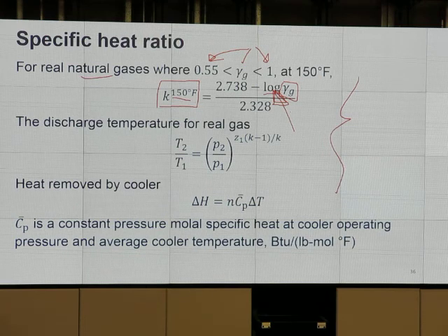So you should know. Okay, next step is, what is the discharge temperature? For theoretical discharge temperature, in theory, discharge temperature actually depends on whether we use a centrifugal compressor or a reciprocating compressor. A centrifugal compressor just spins, a reciprocating unit just pushes back and forth. If we use a different type, the coefficient, I think 1 over eta, is different.